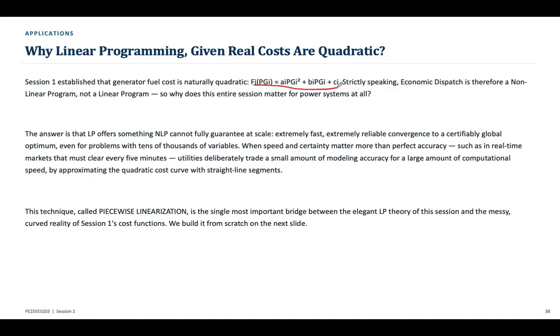See, this is an important engineering judgment here. We do not linearize because the nonlinear curve has become linear in reality. We linearize because a simplified mathematical representation may be sufficiently accurate for the decisions we need to make. So model accuracy and computational cost must be considered together. Okay. Well, piecewise linearization of the cost curve.